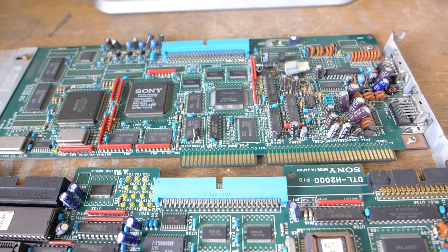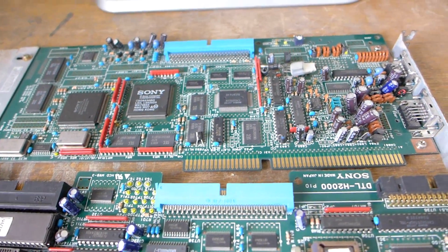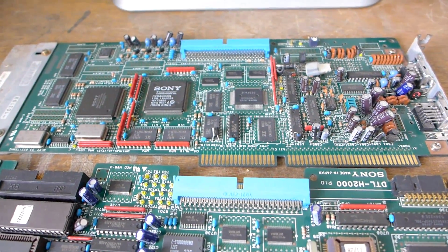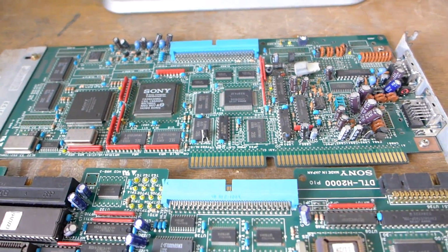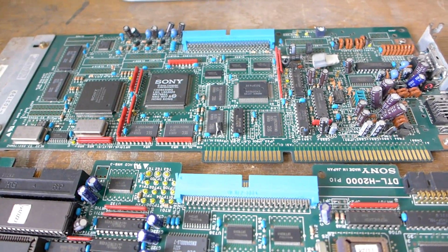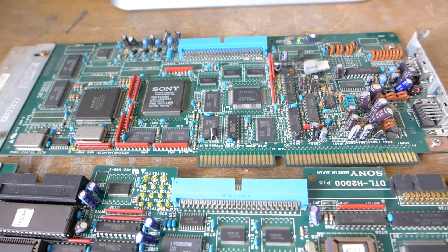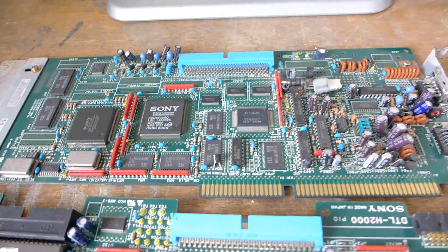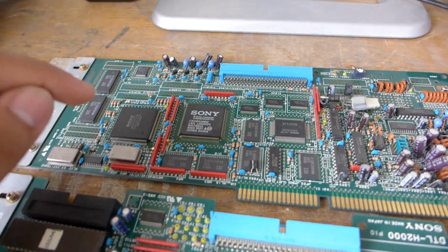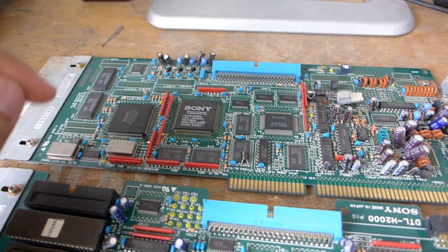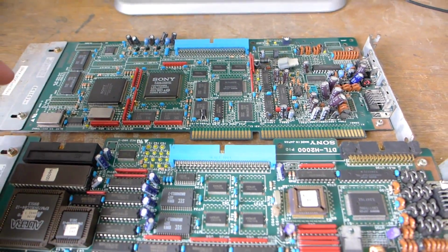Memory writes in the scratch pad, I think, will not work. Would stop working properly in one processor cycle or something. Basically, the scratch pad I/O access is a bit screwy in the ones with the ceramic heatsink on them. But fortunately, this one is the newer DTL-H2000, which doesn't have that bug.